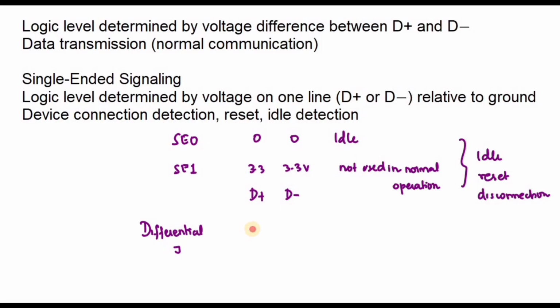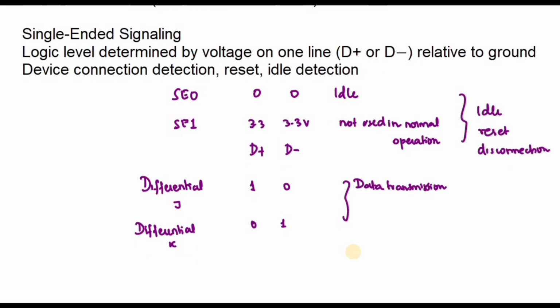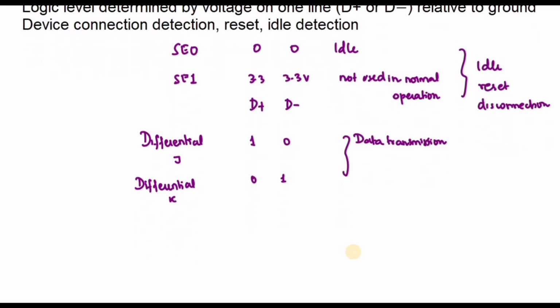This is a very effective way to reduce the noise seen by the receiver, because any noise injected on one of the two wires of the twisted pair is also injected on the other. The receiver is sensitive only to the voltage difference between these two wires, and the noise gets cancelled out because noise is transmitted on both wires.